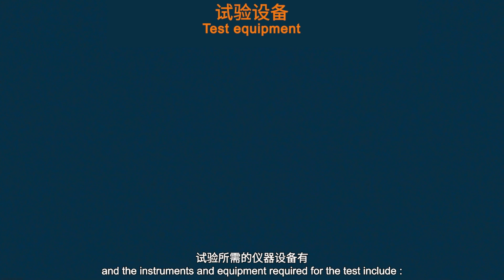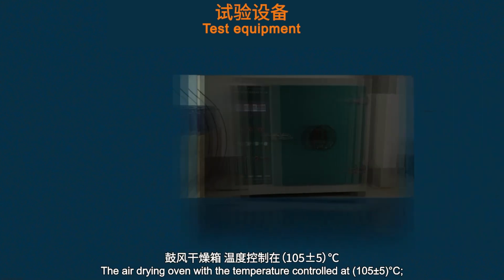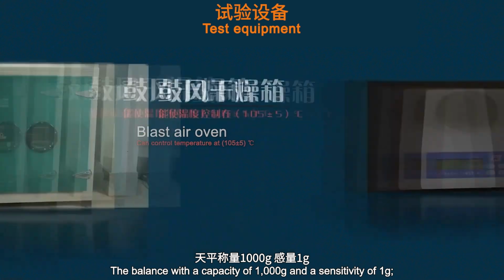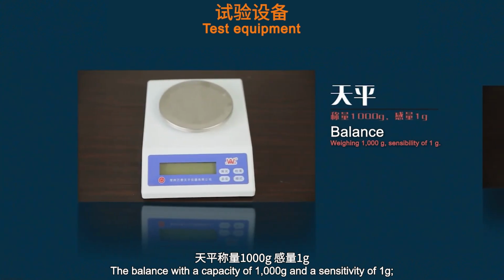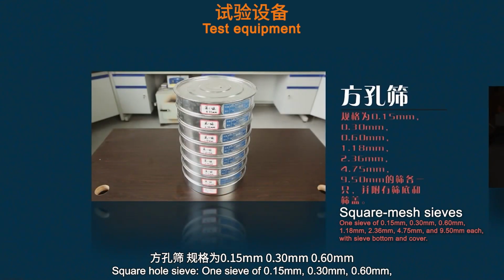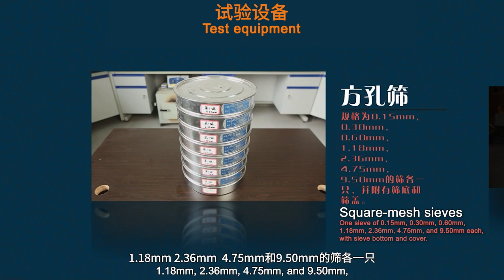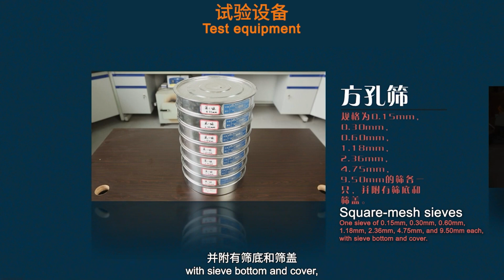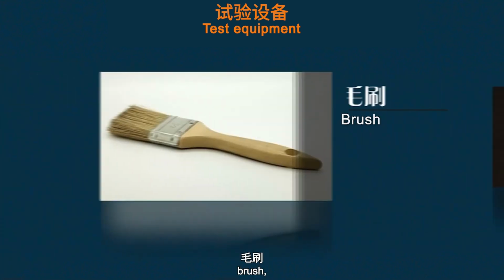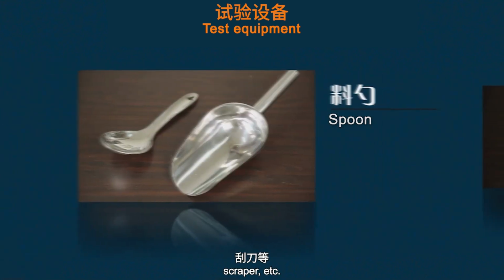And the instruments and equipment required for the test include the air drying oven with the temperature controlled at 105 plus or minus 5 degrees Celsius, the balance with a capacity of 1,000 grams and a sensitivity of 1 gram, square hole sieves, one each of 0.15 millimeters, 0.30 millimeters, 0.60 millimeters, 1.18 millimeters, 2.36 millimeters, 4.75 millimeters, and 9.50 millimeters, with sieve bottom and cover, sieve shaker, enamel tray, brush, spoon, scraper, etc.